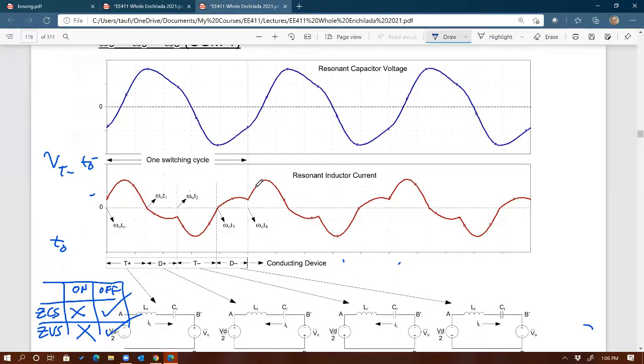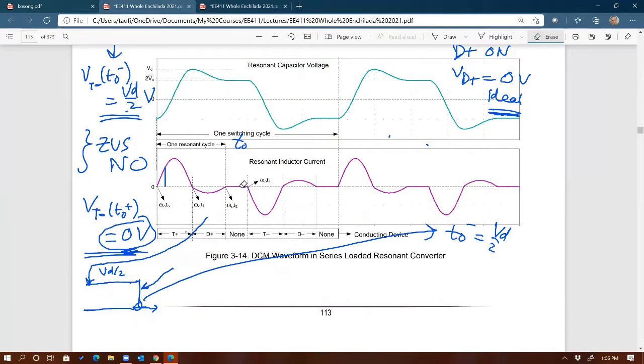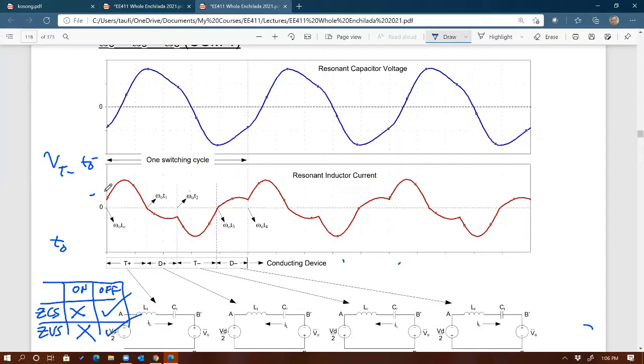If your priority in the design is harmonics, then definitely you don't want to use DCM. That's going to be a lot of noise, especially with the 0 segment right there. That's going to add harmonics. Here, there's no 0 segment, so your harmonics are going to be less. Visually it's more sine wave too. The closer it is to a sine wave, the fewer harmonics you get in the system. Does that make sense? Hopefully.